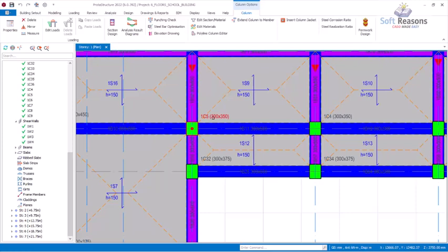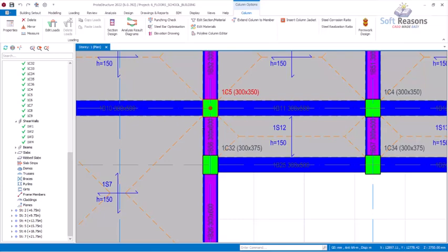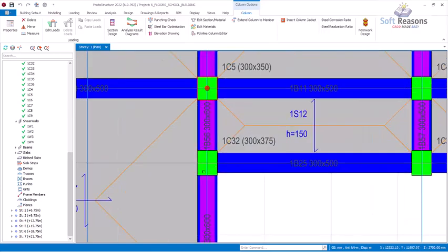Why is this one much higher? This one is higher because you can see a larger panel here, another panel here, and a panel here. But for these ones, the panels around them are smaller. In this one we have other larger panels here. The column that I think is going to be much smaller is this one.